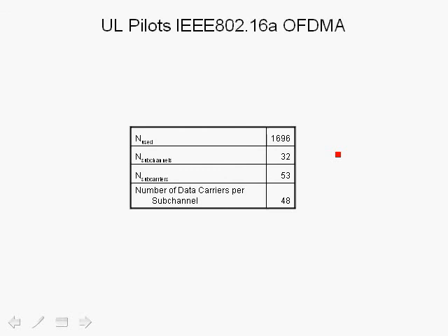Now, since each subscriber station has a subchannel associated with it, then it has to pack the pilots into its subchannels when it sends its burst back up to the base station. So the position of these pilots changes on a subscriber by subscriber basis. That's the idea about the variable pilot locations in the uplink data burst.